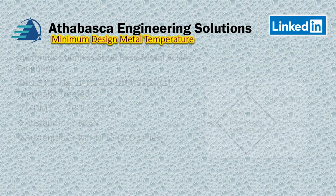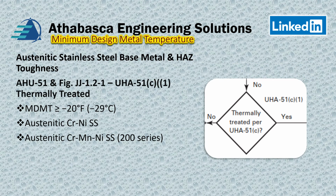So let me skip on to another part of this chart. Basically, if they ask you a question, has it been thermally treated? Which means a solution treated for stainless steel, and there's some definitions for that, and that's to make sure that the grains are nice and even. If that occurs, you get a credit to minus 20 degrees Fahrenheit, and that applies to the different types of austenitic stainless steels.